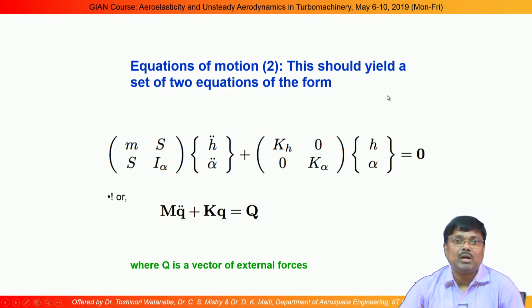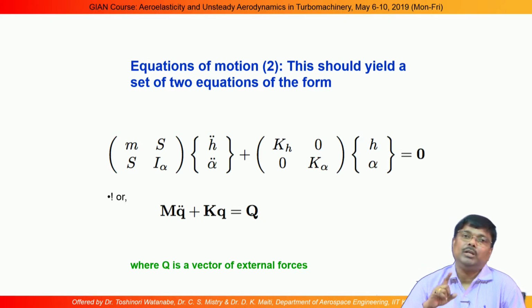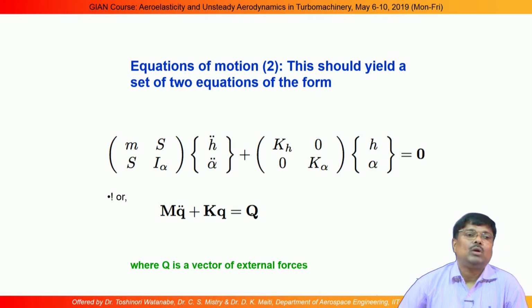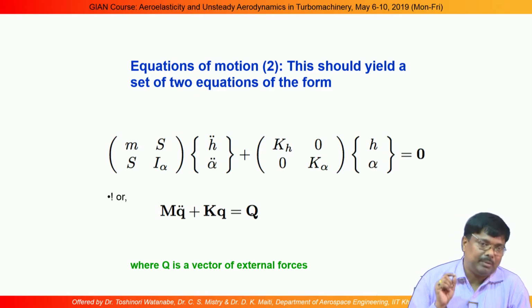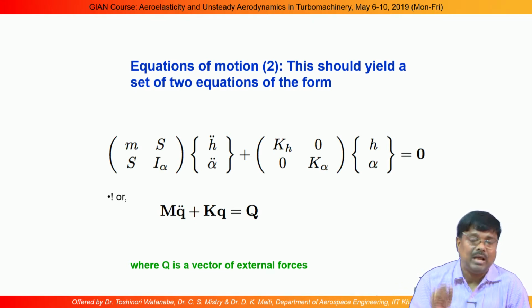The first equation we got will give us the modal analysis, the frequencies and the mode shapes for a structure where there is no damping. That is why, when there is no damping, the frequencies and mode shapes we extract, we call the normal mode analysis. Why is it normal mode? The damping actually changes the orientation of the forces, if we see the vectorial representation of how the inertia force, the stiffness force, and the damping force are acting.